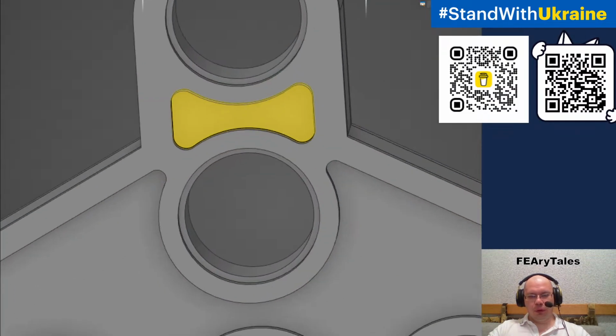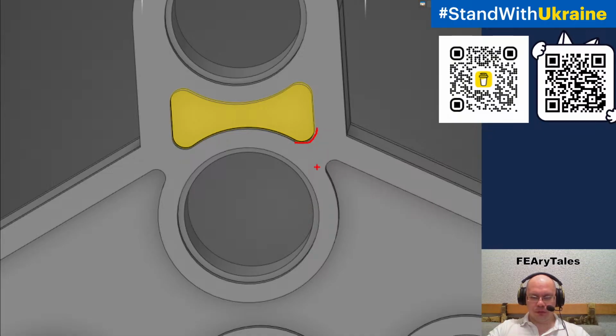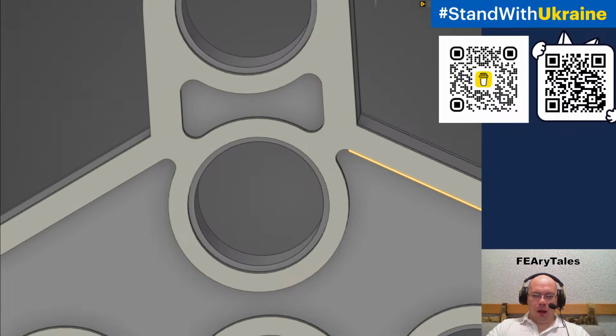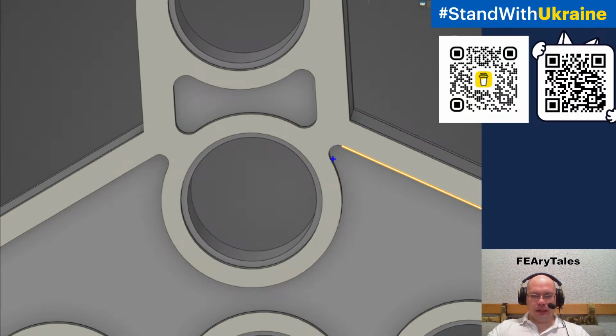And if you leave those rounds on those objects, you will have a very big problem in these places, because here we have tangency, and as a result of tangency we will obtain a very bad quality mesh, especially when we create a smaller mesh size.